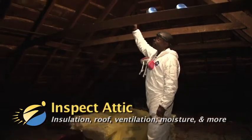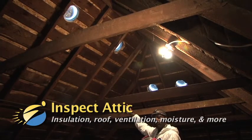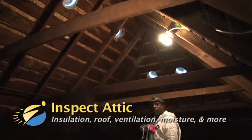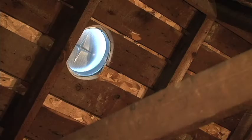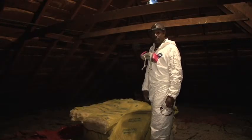We start at the top, looking at the roof decking. Do we see signs of moisture? Here we see some signs of moisture, but we also see that we have a new roof. So probably there was some leakage and that's why the homeowner replaced this roof. Next, we take a look at our roof vents, just to make sure that they're open. Because sometimes we'll see roof vents from the outside, but when we get into the attic space, the roof vents aren't open. Next, we make our way down to the insulation.